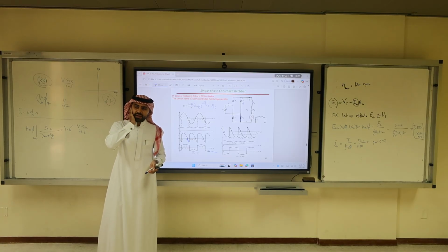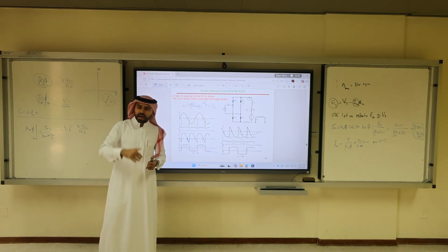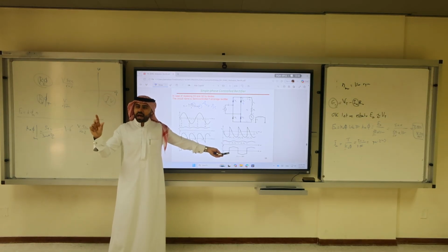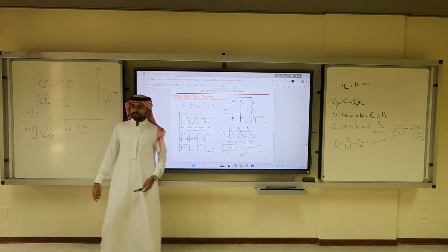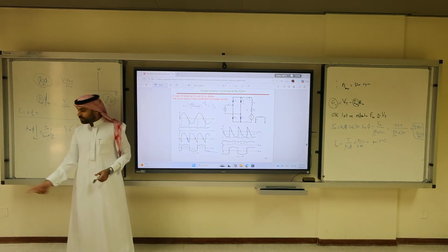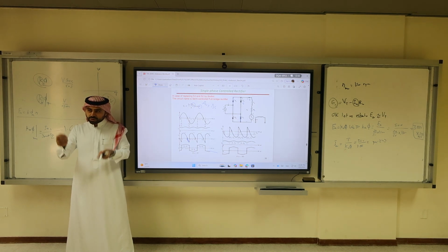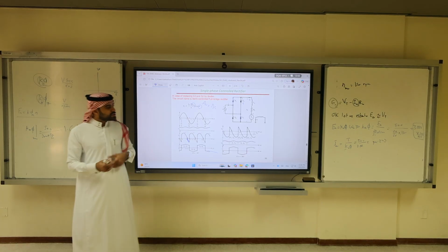How did we enter dynamic braking for induction? You remember? We had to wait until we slow down. But here, for a DC motor, by just changing the firing angle, I can trick the machine to have a negative DC from an AC supply. It doesn't mean it will rotate counterclockwise. It means we are entering regenerative braking.